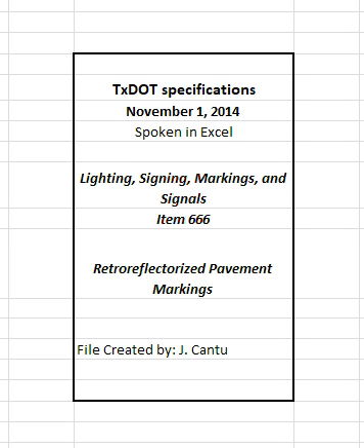Measure each line in both directions for center lines on two-way roadways, i.e., measure both double solid lines in both directions and measure all center skip lines in both directions. The spacing between each measurement must be at least 100 feet.